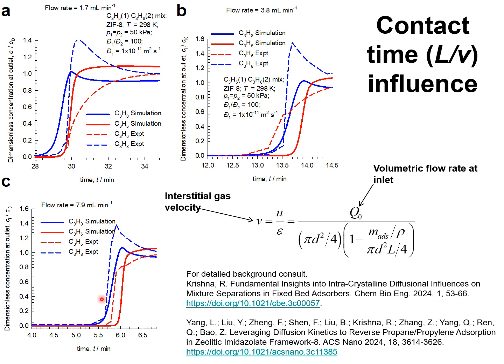In all 3 cases, there is good agreement between the breakthrough simulations and experiments, and we see that with increasing flow rates, i.e. reduced contact time, the breakthrough of propene occurs later than the breakthrough of propane, and this is desirable for kinetic separations of propene-propane mixtures.